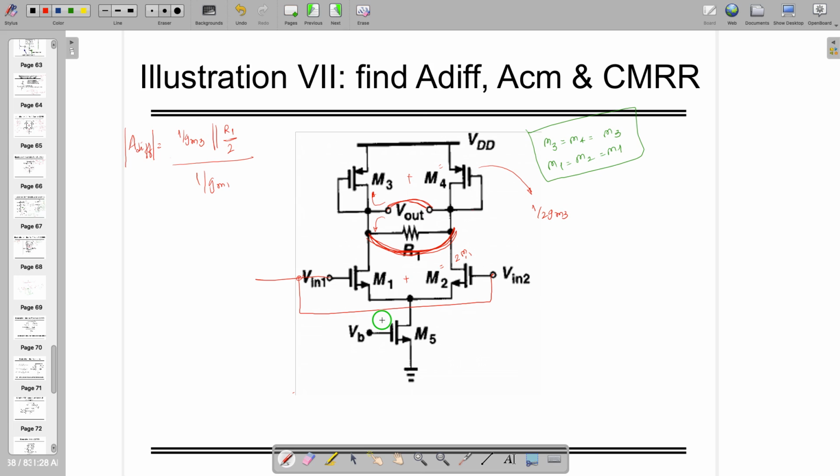And you can write down the complete common mode gain as follows. Looking into this, by the way, the resistance offered by this current mirror is RO5, where Vbias is the bias voltage. So RO5 plus 1 by, since two gm quantities are in parallel, it's going to be 1 by 2 gm1, and looking upside, it's 1 by 2 gm3.